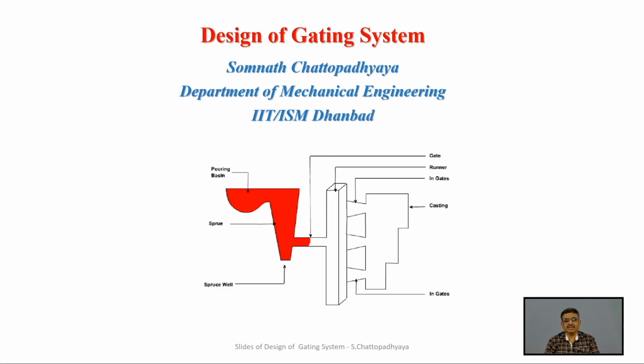Molten metal will not reach the cavity appropriately in the desired way. So what happens? It will be a short casting, and it will be a defective casting. So one has to be judicious in designing those gating systems. There are many uncertainties whenever liquid molten metal is poured into the system for casting. The flow has to be ensured, and there are a lot of problems, a lot of possible choking areas, if it is not done appropriately.